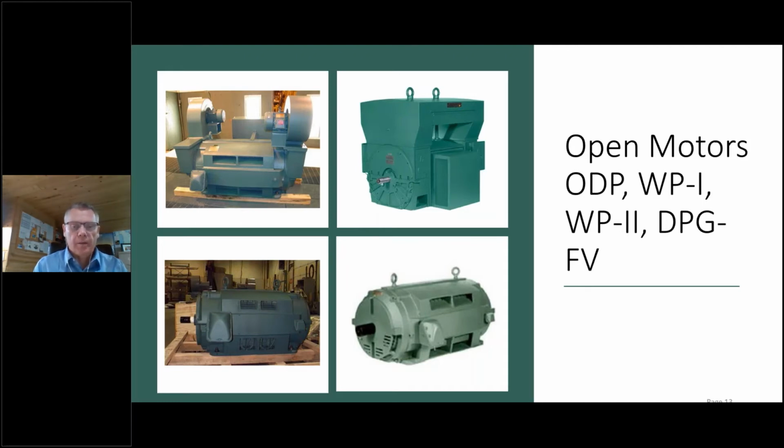As we rely on internal fans to cool the motor and run it slower and slower, it's not getting the same airflow over the motor, so the piggyback blower will continue to blow constant speed air over the motor.